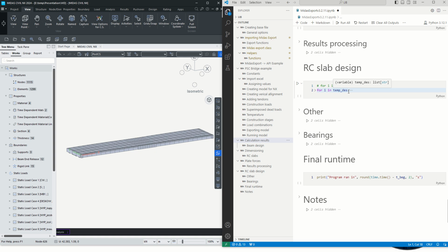one of the good things is that the generation of tables, as we have seen in MIDAS Civil NX, has been significantly improved for the envelope tables. The time has been shortened, so it's a lot more efficient for pulling out the values. But the nice thing is here we can now create a loop and pull out various tables at once. The downside of doing it in MIDAS Civil, a very small downside, is you have to click through each time, and there's a certain overhead for actually having to do all the things. If you do a loop, you can do various loops all at once.